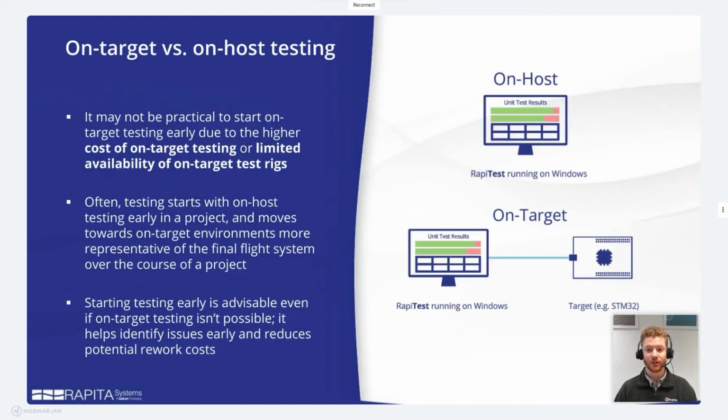One reason you might be doing on-host testing at all is, again, as I mentioned earlier on in the development process, the hardware may not be finalized, available, etc. So the ability to start testing on host is pretty crucial. And if you are able to reuse your test cases with an on-target test as well, then that's a huge amount of value because you're not repeating the work of writing those test cases. And again, you're detecting errors earlier, they are cheaper to resolve. If you need to change your requirement, it is much better to identify that early because there's a knock-on effect in changing requirements.